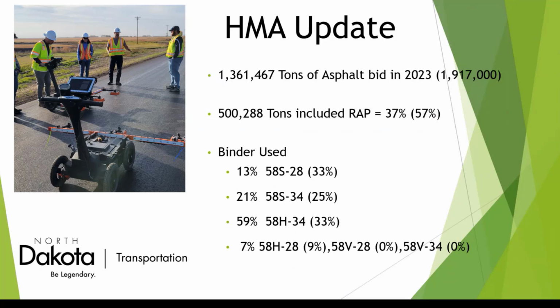But I think people are walking a lot more gingerly. You can step over dollar bills to pick up pennies sometimes, if the performance of your RAP mix doesn't equal the performance of your virgin mix. And that can be done, and has been. NCAT and others have shown that, but you really have to engineer the mix much more closely, and under our old way of doing it, 4% air voids, for example, and so forth, it was a lot harder to do that.